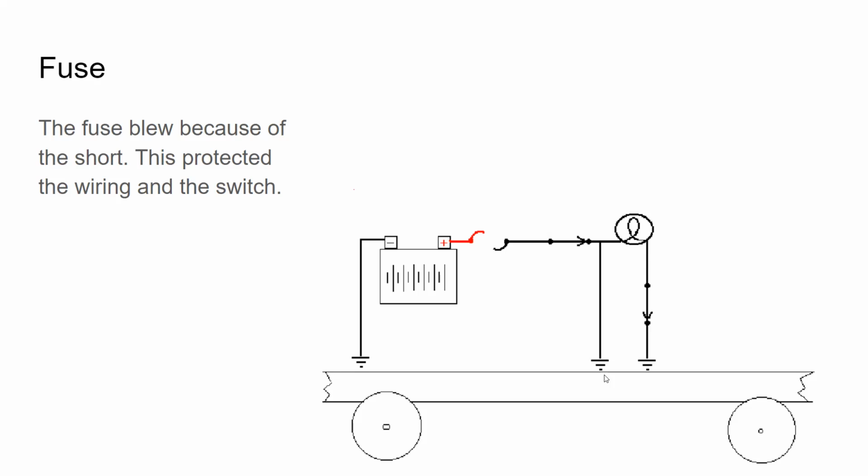If we have a short circuit to ground from a positive wire, that creates a runaway effect of current. And just like current flowing through a light bulb will cause it to glow, if we have a short circuit, some part of our wiring harness would start to glow unless we interrupt that circuit. That's exactly what the fuse is for.